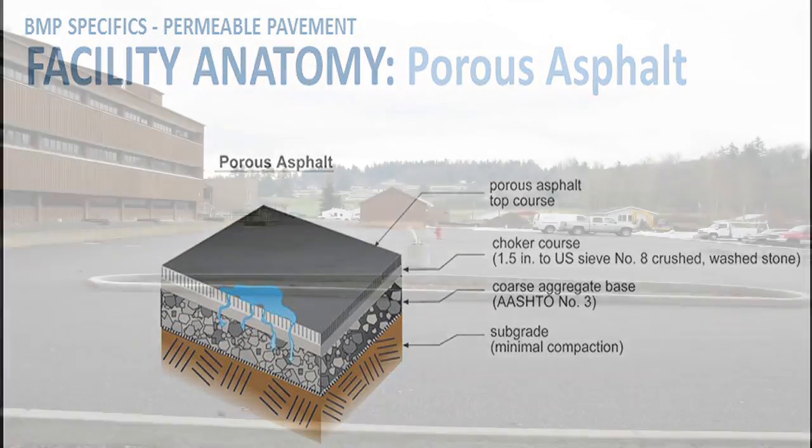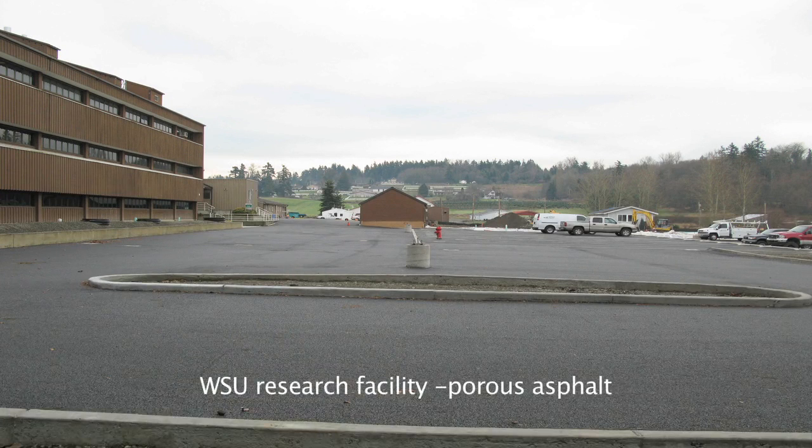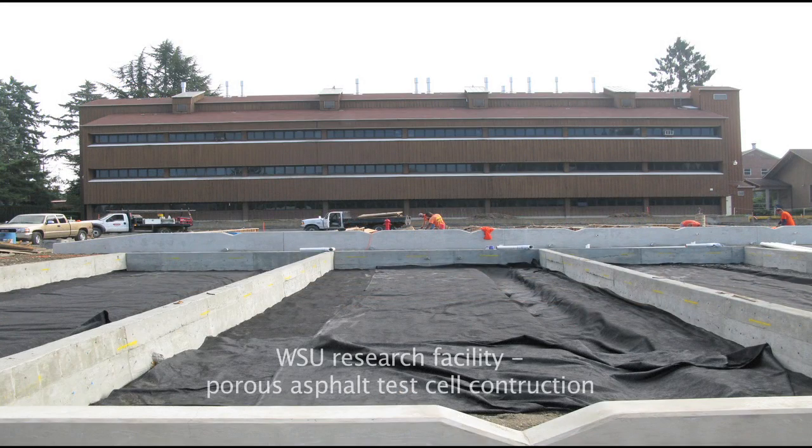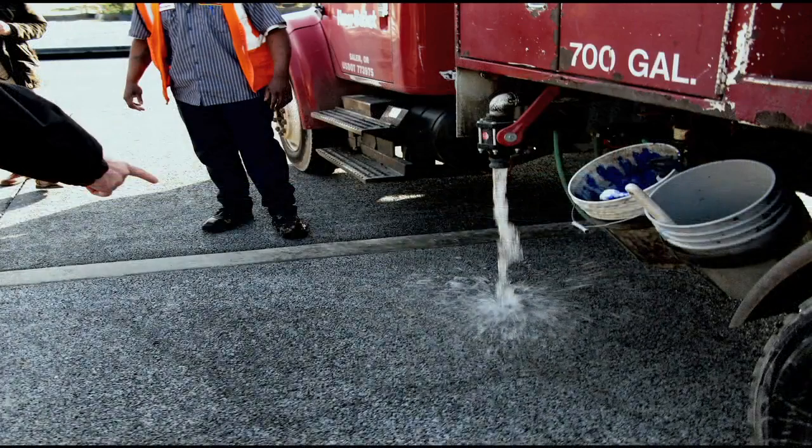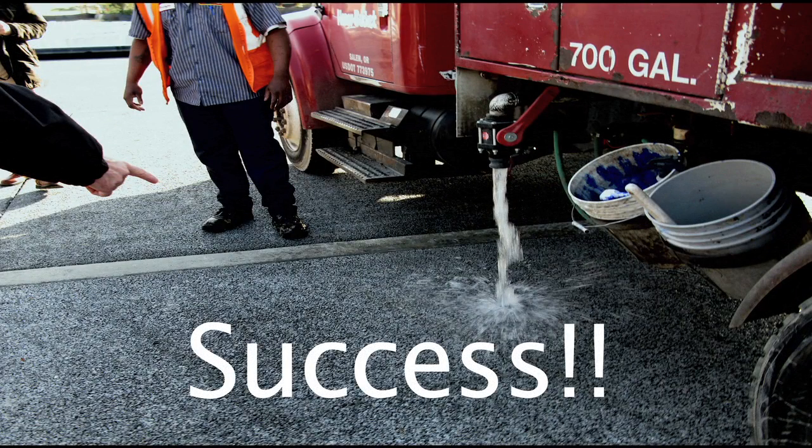However, the industry right now around placing porous asphalt successfully, I think, lags all of the other practices. So, for example, at the Stormwater Center down in Puyallup, I think it was a pretty successful installation of porous asphalt that is holding up well. I think there were also several installations around Puget Sound the past few years that have not been as successful. Placement isn't done right, and if the mix design isn't using stiff enough binder, it can be problematic.